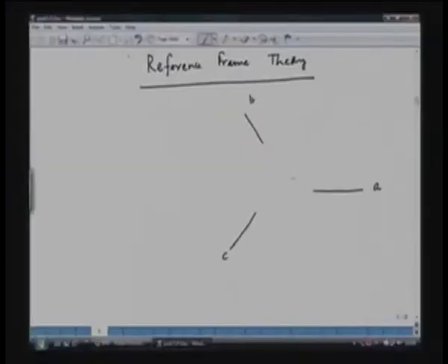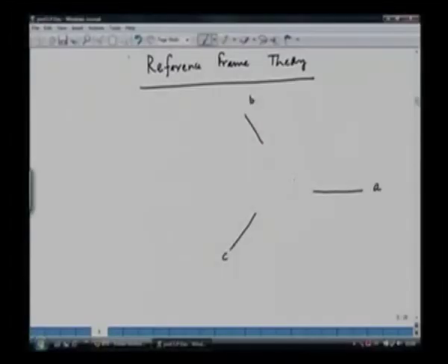So we can say that when we convert this into a DQ system, it is always orthogonal. This is my D axis and this is the Q axis, and this angle that it subtends with the A axis is theta, and the reference frame is rotating at a speed of omega radian per second. So this reference frame is not stationary, it is rotating at a speed of omega radian per second, and this is called a rotating reference frame.